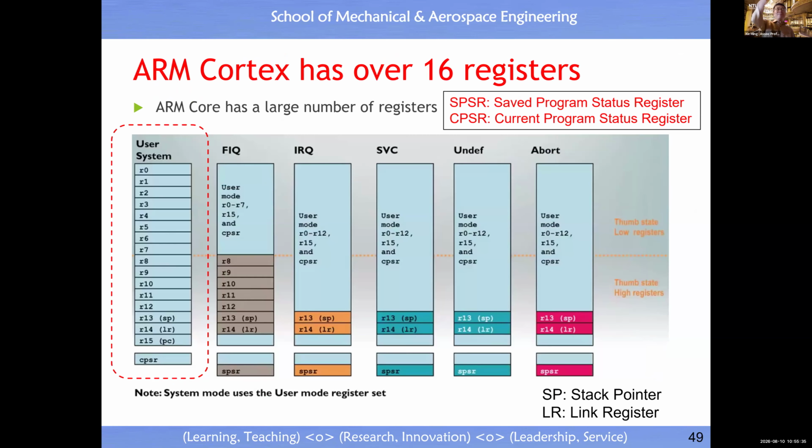So this is a working space, working memory. And the working memory, we call them a register. Now you see you have registers R0 all the way to R15. So it means what? You have 16 working memories, right? Each register has 32 bits, understand? That means each register can store 4 bytes, okay? And registers 13, 14, 15, you cannot use because they have a dedicated function.